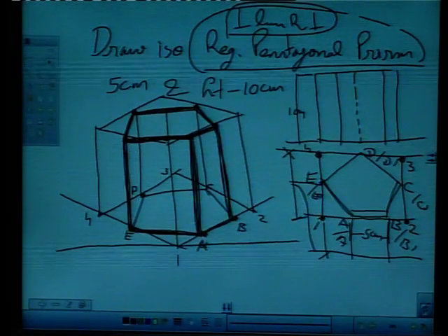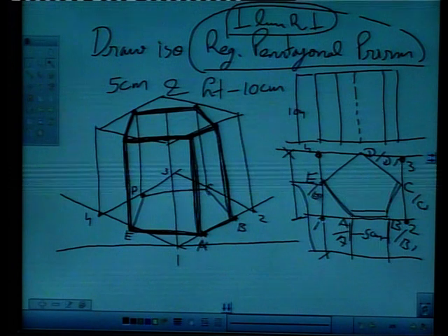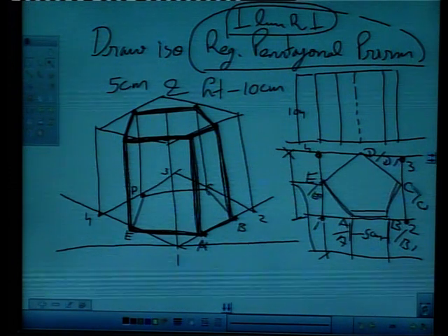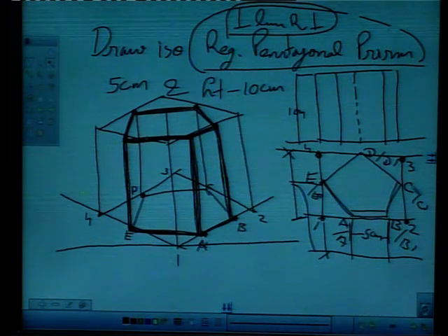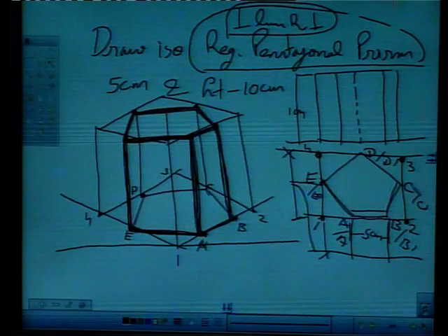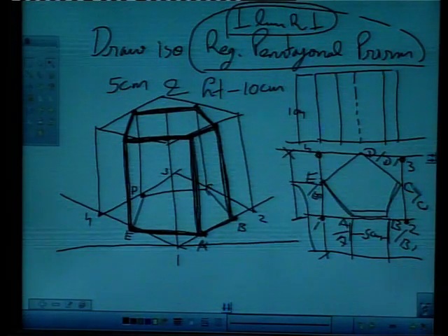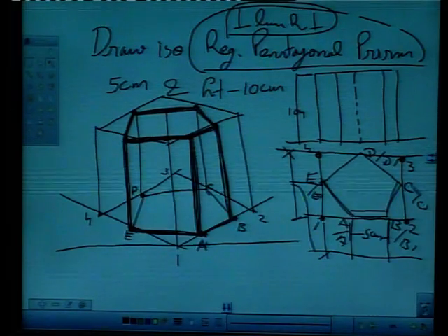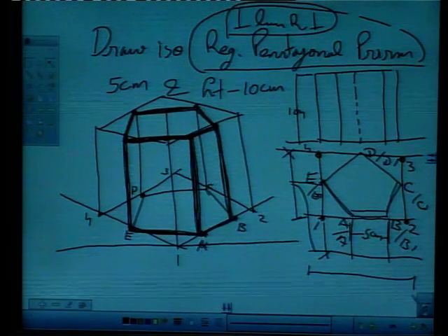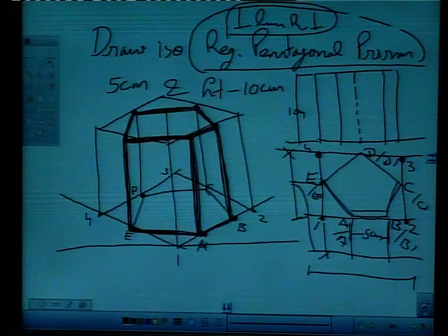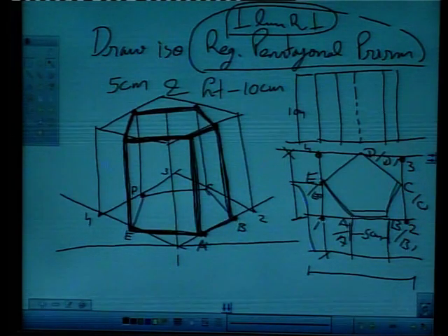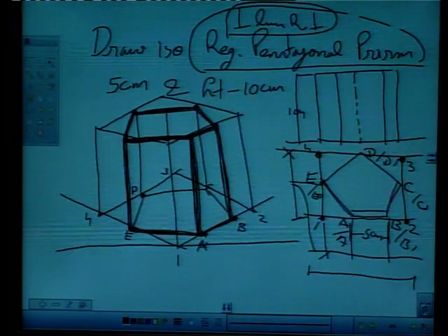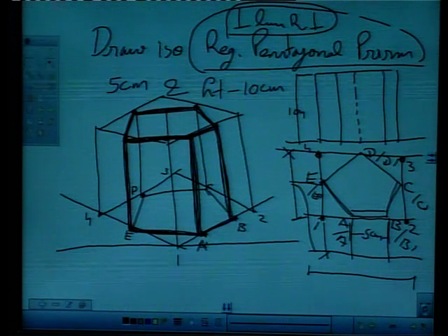What we have done here is, we have simply enclosed our pentagon in a cuboid, right? And measured this cuboid and drew its isometrics, and then from the cuboid worked out the points A, B, C, D just simply by measuring from this drawing, this plan. So this plan must be to the scale, right, and drawn accurately. And for taking points, we can use compass or scale. We can measure this point with scale or with compass. I hope it is clear to you, students.